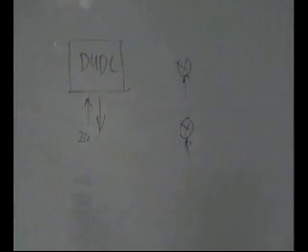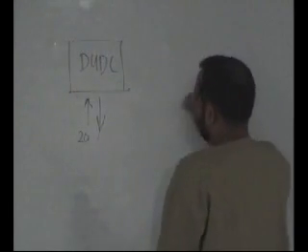So let us see what is involved in bringing the sampling rate down and up. And we know the motivation. The motivation is that you got to do it, because this is at the front end of a receiver. If you don't do it, you have more samples than what is required, so your whole receiver will be very expensive. So you do this to reduce the cost of your receiver.